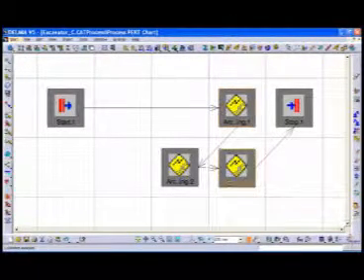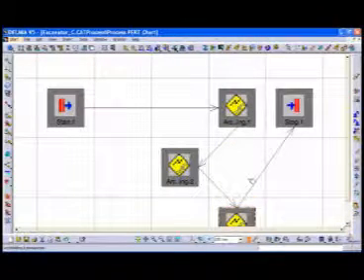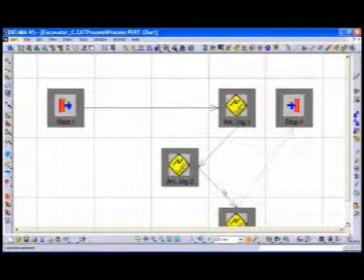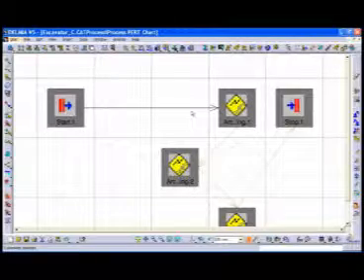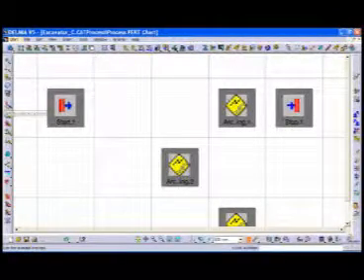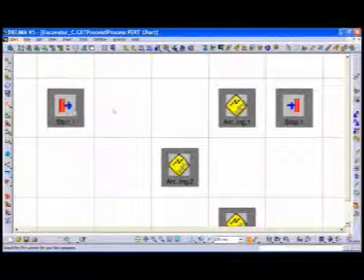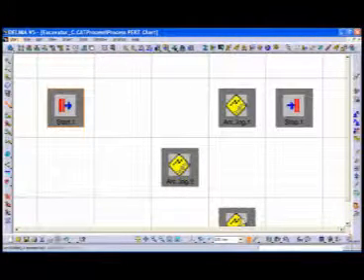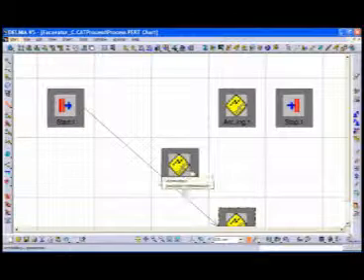To orchestrate a work cell simulation, we program it in a PERT chart. In the PERT chart, we can arrange the sequence of operations for the entire work cell. Here we can execute device tasks as either in series or in parallel operations. If we want the work cell sequence to execute differently, we just delete the arrows and redraw them in the PERT chart.